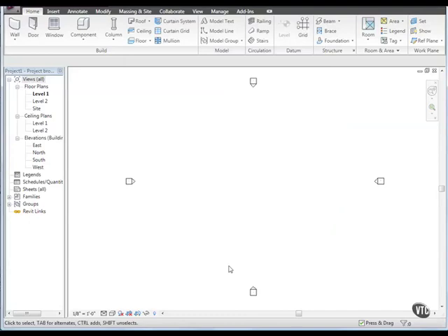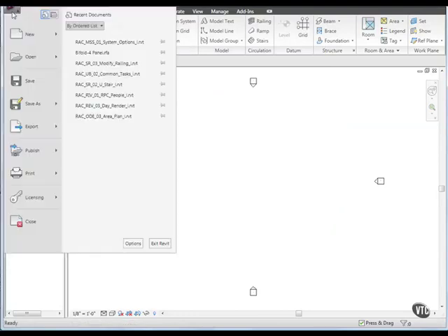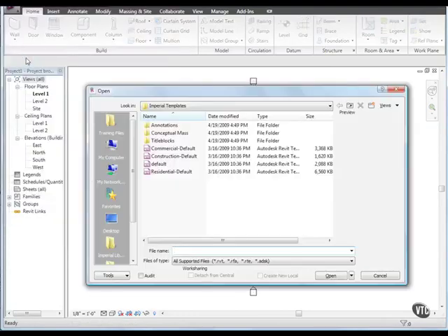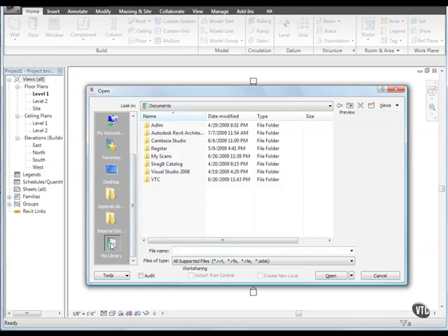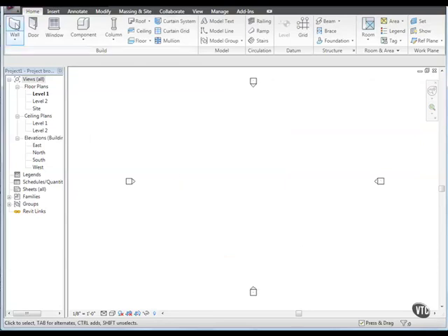and then click the menu Browser and select Open. In the left pane of the Open dialog, click the My Library icon. Notice that Revit Architecture navigates directly to the library path. If you work in a large office, you may want to set up an office library on a network path to increase productivity and maintain office standards. Click Cancel. Then go back to the Options dialog box.